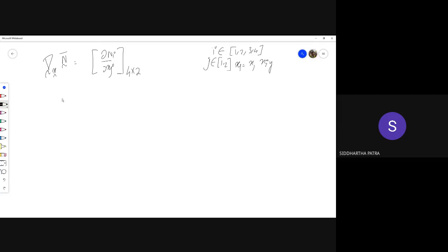So this matrix, as we showed in the earlier class, is a combination of this: gradient of N with respect to xi, multiplying J inverse. If you revisit Wednesday's class, you will see how this turns out to be true, simply using the chain rule. So this is what you are supposed to get.